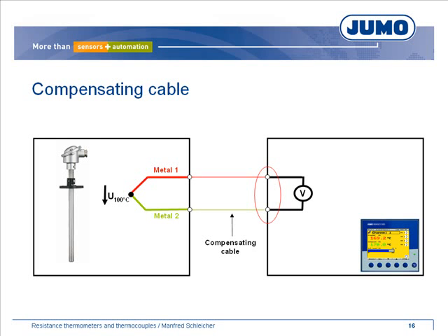The internal PT100 measures the temperature of the reference junction and the measurement result is corrected. You have to use the corresponding compensation cables. Please consider the polarity.